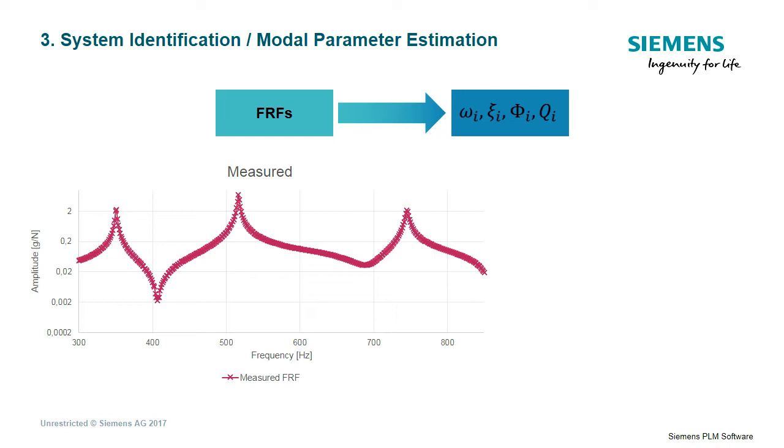We will not go into the details of the modal parameter identification algorithm itself, but the general principle is very simple: find the combination of modal parameters which maximizes the fit between the measured FRFs and the ones calculated from the identified modal model. It should be clear now why the fundamental equation was introduced at the end of the introductory part.